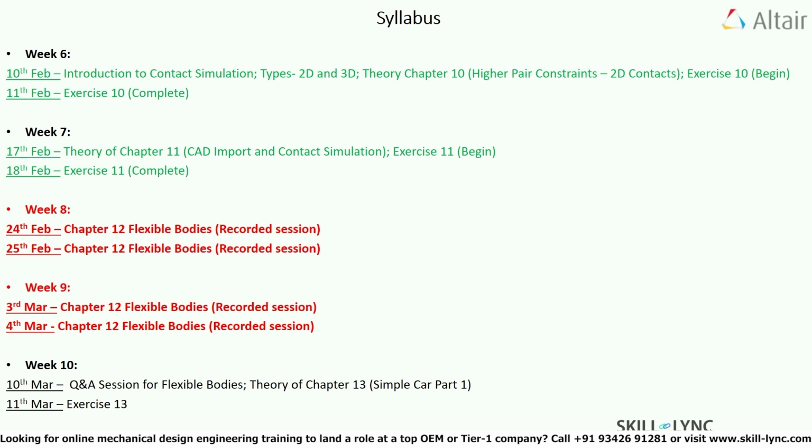We started with the basics of model building and then we simulated the free falling of a stone. We then built a simple pendulum and continued building our final model to finally simulate the motion of an automobile trunk lid using the 4-bar mechanism. In week 6, we concentrated on the higher pair constraints and simulated the cam follower mechanism using the CV-CV joint. In the last week, we covered the topic of contact simulation, which included both theory and a practical hands-on demo for simulating the contact forces acting on a ball bearing.